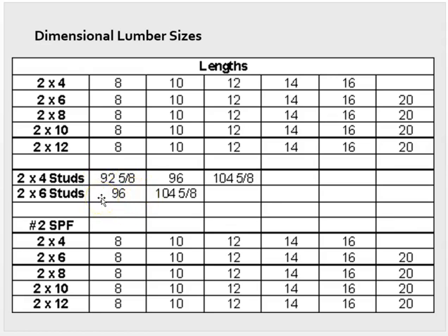And all this is in the effort to put an 8-foot piece of drywall in the living room. So the pre-cut stud, the 92 and 5/8, plus the 3 sill plates will get you up to that 96 inches, and then probably a little leeway above that to fit the 96-inch piece of drywall. So that's where it all stems from, and it's a common pre-cut stud.